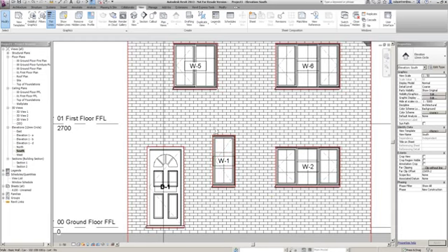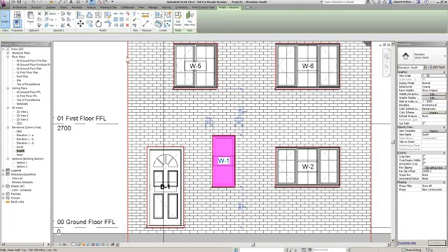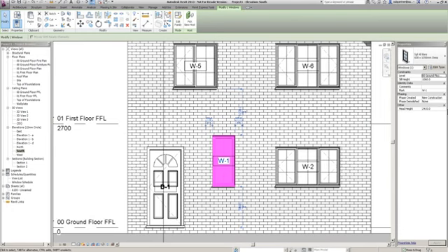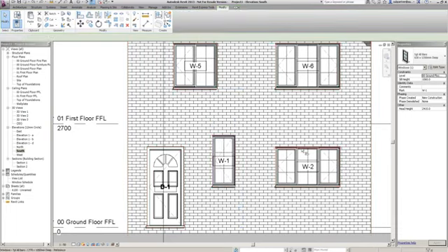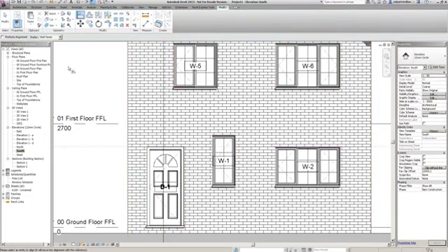Okay, now I can change this in my elevations or plans using several tools. I can highlight it, just change it in here to 2110. Done. Okay, so Control Z that to take that back up. I can use my align tool just to align that to the top of there like that. Okay, you know how to do that.